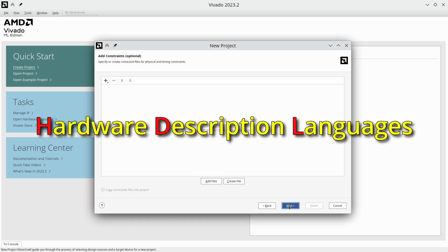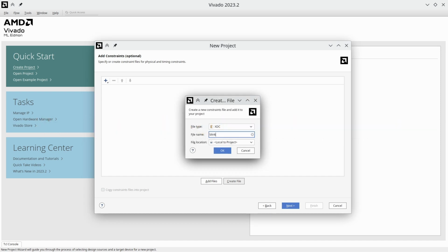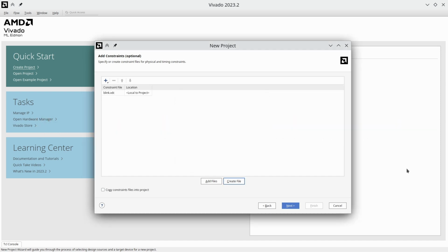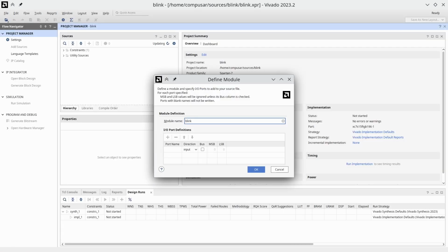As usual, we'll focus on programming the FPGA using SystemVerilog. Other HDLs have similar constructs, though syntax will naturally vary. The task we'll want to achieve is to blink an LED at 1 Hz. Naturally, the first step is defining a top-level module in which our LED will be an output signal. We'll also need a clock to work with. Our board provides a clock, so we'll define an input signal to receive it.